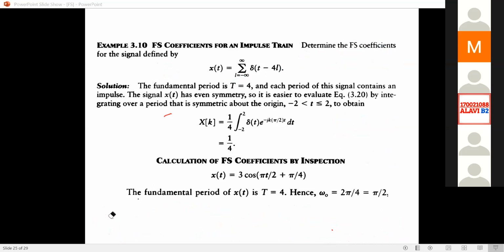Another similar thing we have discussed earlier for the case of discrete time signals. If your signal is a general type of periodic signal, then we can use this mathematical technique to extract the frequency information of the signal, because this cannot be seen in the time domain. But if your signal is itself given in the form of sine and cosine functions, and they are harmonically related, we can easily determine what Fourier constants are there in the exponential form.